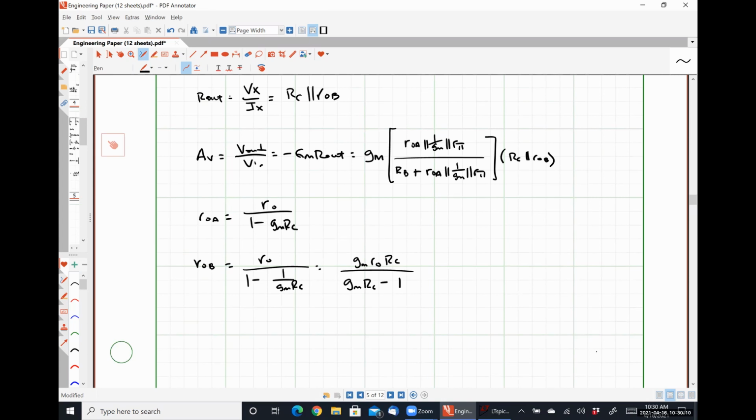All right, so you guys feel comfortable-ish with applying Miller's theorem, splitting up feedback loops and all that kind of good stuff. So on Monday, we're going to get into our frequency analysis. We're probably going to do some low frequency analysis and then get into the high frequency models of our transistors, which is where we're going to see lots of weird capacitors between terminals, which is why we need to use Miller's theorem to make these things remotely manageable.